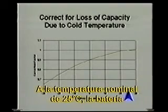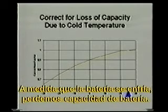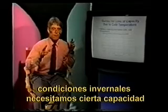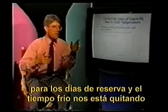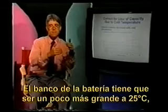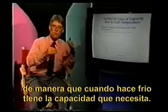At the nominal rating temperature of 25 degrees, a battery has its nominal rated capacity. As the battery gets colder, we lose battery capacity. If the battery warms up again, we'd have that capacity back again. But the point is, we're looking at a system operating in a wintertime condition where we need a certain amount of capacity to give us our days of reserve. And cold weather is taking away some of that capacity from our battery bank. We have to actually size our battery bank slightly larger at 25 degrees so that when it's cold, it has